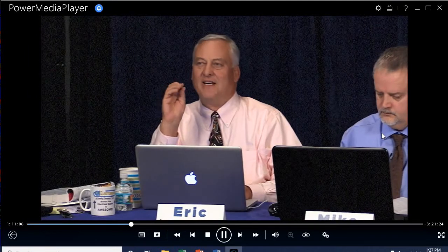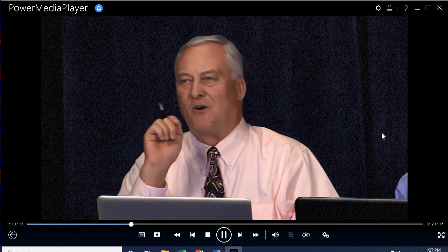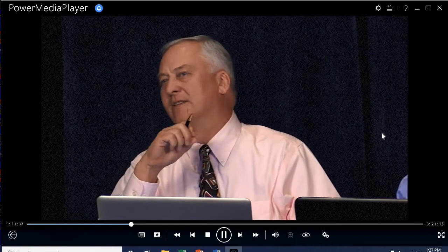Eric? Just want to mention when you talk about services that it's extremely important to realize that not all buildings have services. That's important to know. So if it is a service on a building, it's covered by Article 230. If it is a building fed by a feeder, it's covered by Article 225.